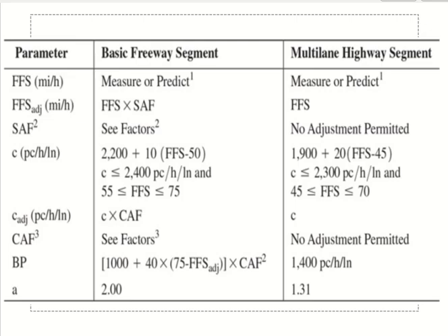Now, with the new breakpoint, can I still use the free flow speed? I can still use it, right? Yes. With the new breakpoint, I can still use it because the new one is also higher than vp. But the density will be from this new free flow speed now. So what is my new density?